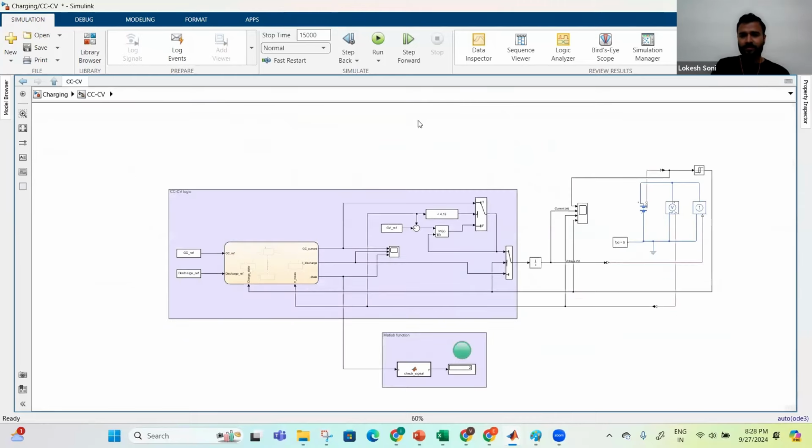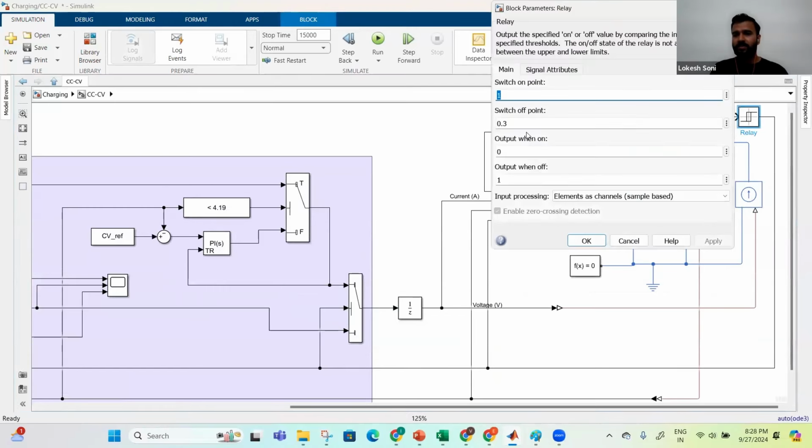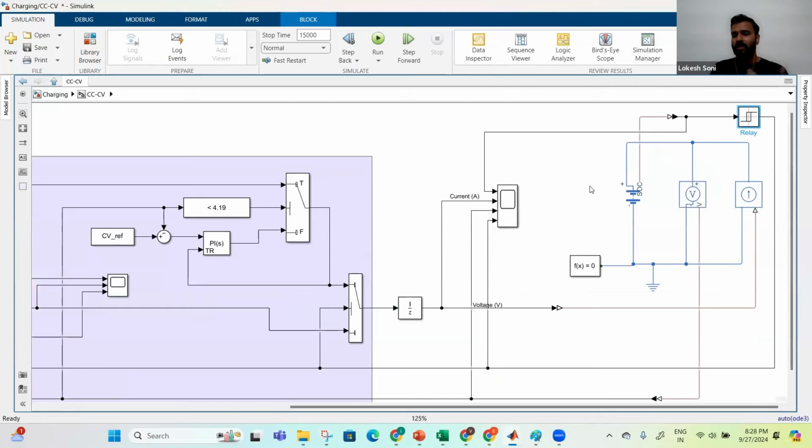I guess it's not required right now. So you see, this is a battery. This is voltage measurement. This is a current source. SOC I'm taking out. What I've defined here is if SOC is less than 30%, I would start charging. If SOC is 100%, I would enable discharging, so that both the charging and discharging phases can be seen here. This trigger is activating the switch.